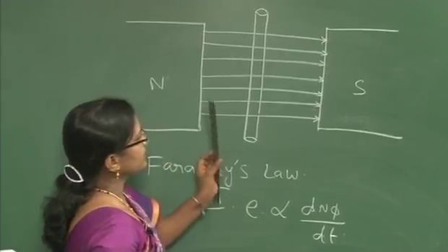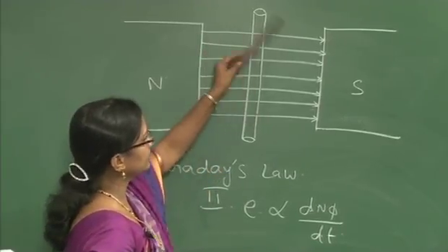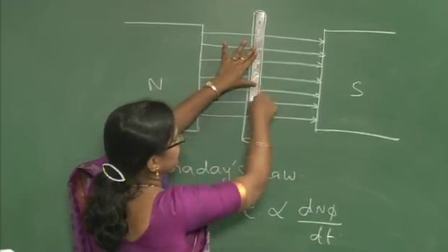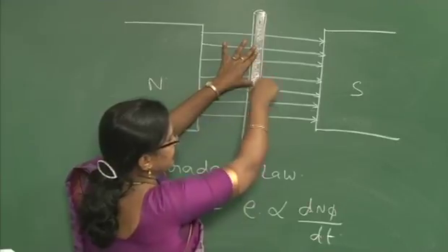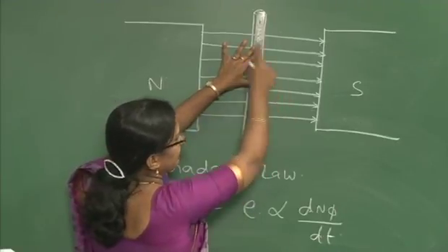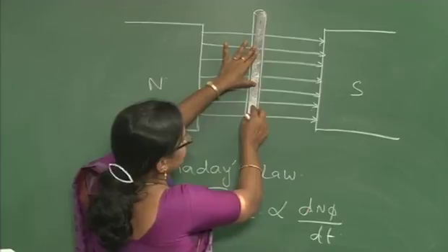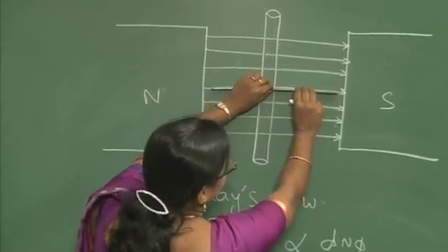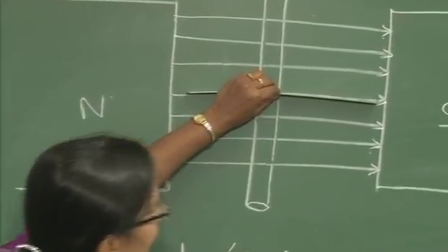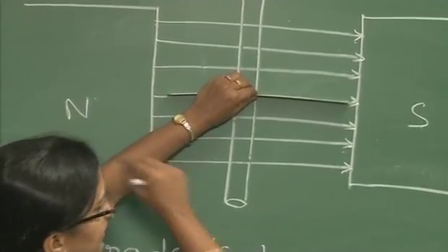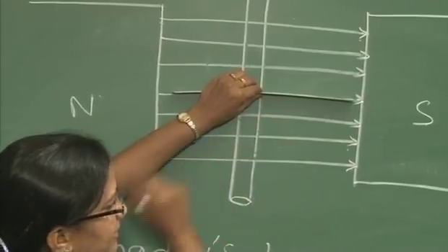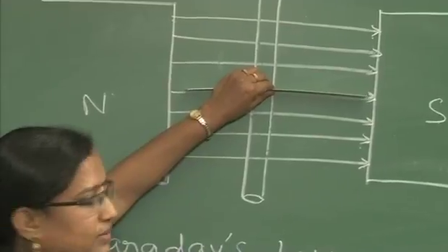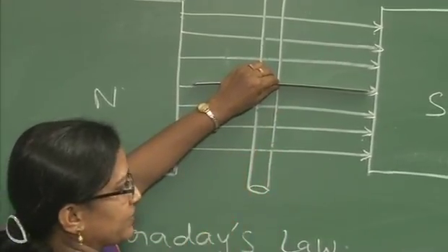When the axis of the conductor is exactly perpendicular to the field, the maximum flux will be linked. Suppose both sides of the conductor are parallel to the magnetic lines; here the magnetic flux lines cut by the conductor is 0, so the EMF induced is 0.